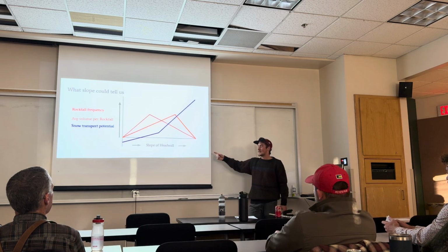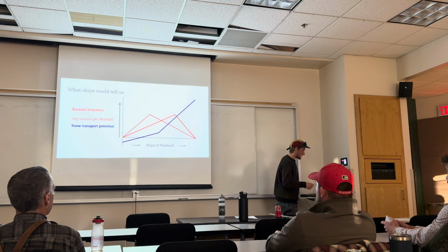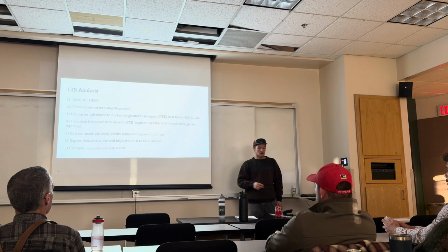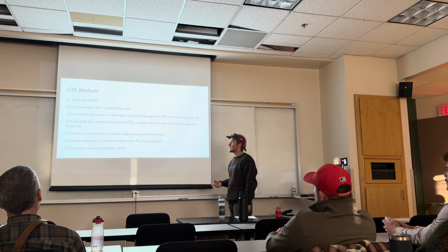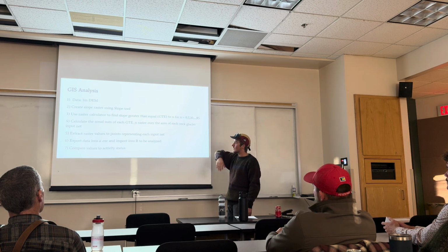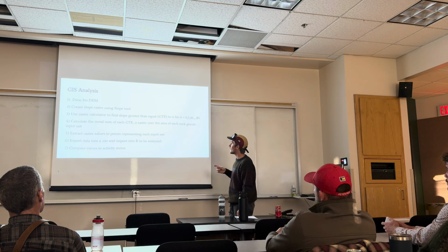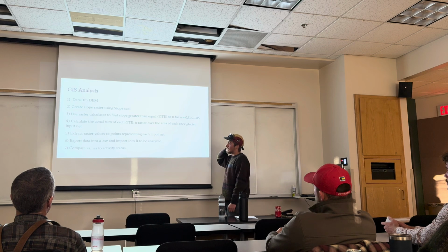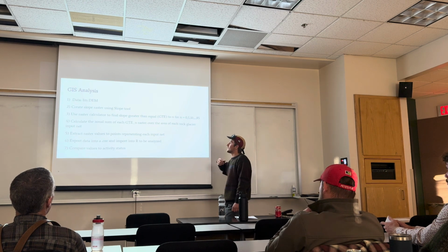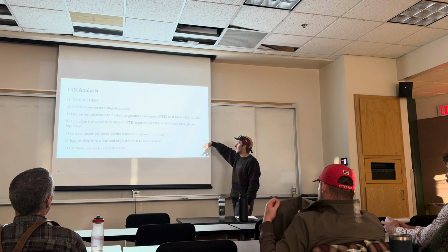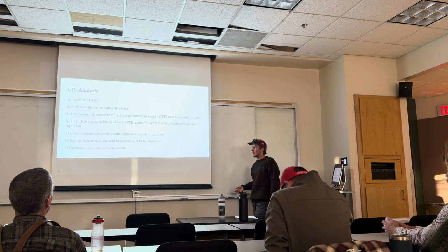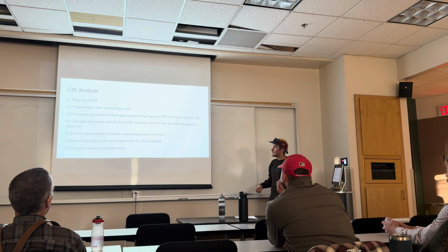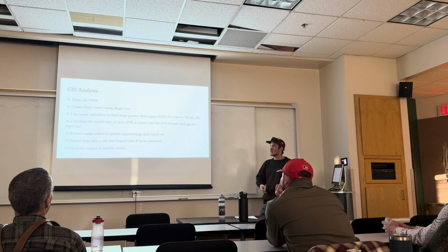So, let's start looking at slope and how that can affect rock glacier growth. As I said, I take my 1 meter DEM raster and make a slope raster out of it. This won't mean much to most people, but if you know GIS, this will hopefully make sense. I took the raster calculator and found the slope greater than or equal to a certain slope value n. N is binned in 5, so it's 0, 5, 10, up to 85. So now I have 16 rasters, starting from slope above 0 to slope above 85.